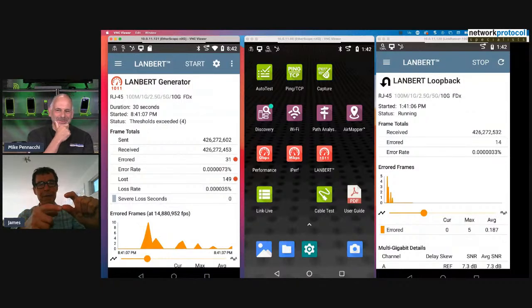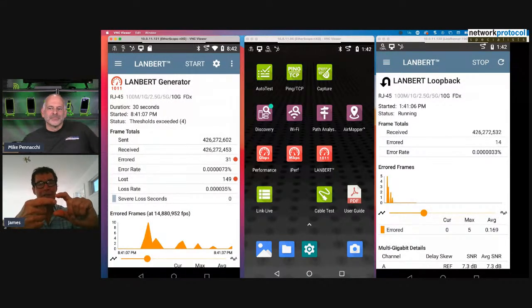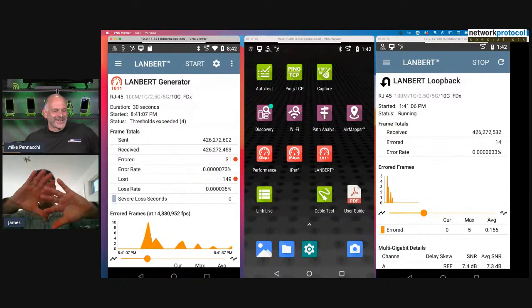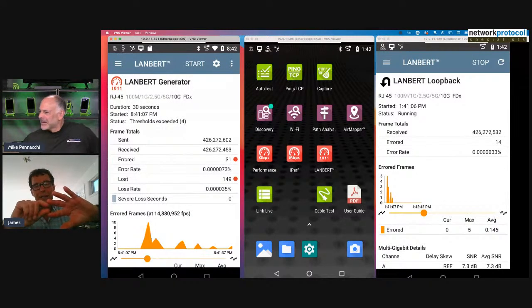And then when they got to 100 megabit, they went to an MLT3 coding, right? So suddenly there were 3 different levels to discriminate. Same voltage swing, let's say 0 to 5 volts, but now there's 3 levels to discriminate. Well, then when they got to gig, it was PAM5. Now they were trying to differentiate 5 levels, same voltage swing. So you think about it, every time you do that, the amount of voltage between levels gets narrower and narrower.